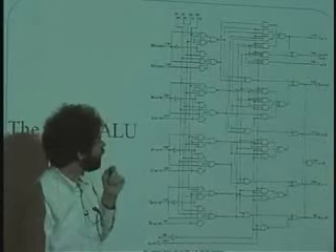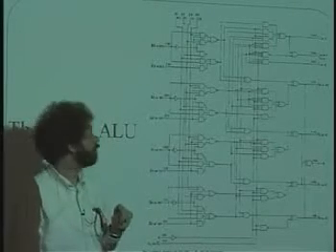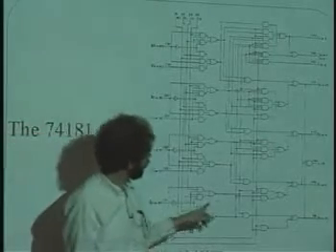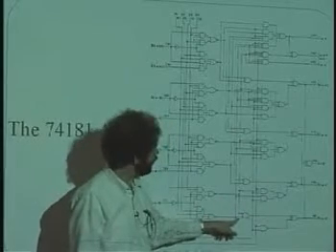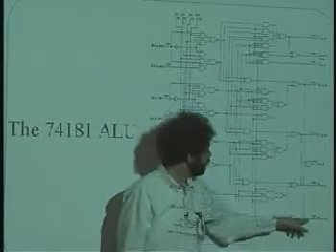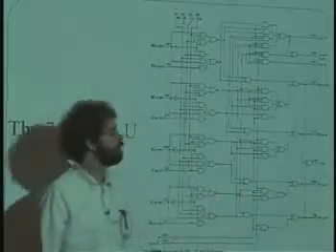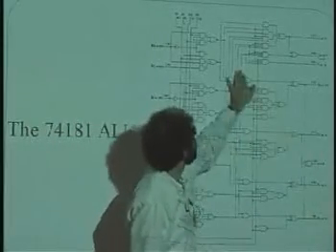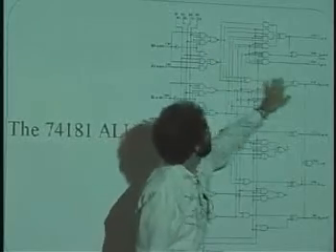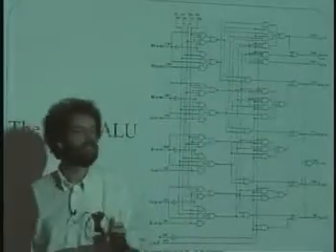Now, how do we generate the sum bits that come out? Well, we seem to be taking some kind of an XOR, here's an XOR gate of G and P, and XORing it with a little bit of other stuff, and then there it comes out. Again, the same kind of thing here, XOR coming out, XOR going out, XOR of G and P that go out, and that's the sum bits.